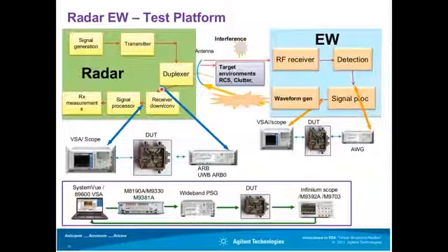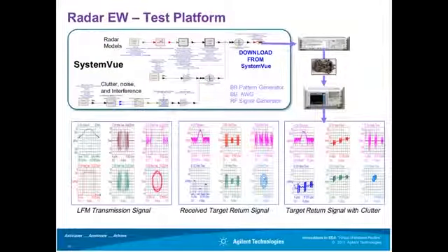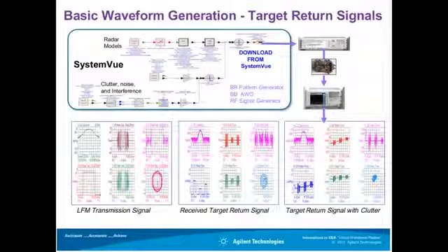Because at each point, we can use a link from simulation to hardware to generate a hardware test signal. And we can capture the observed raw waveform back to system view continuously to do the signal processing and the measurement, and get the hardware test solution. So that's the point. We can use this in two ways.